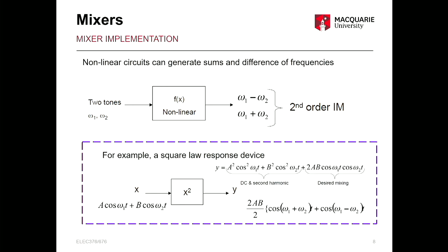So implementing the mixer. We told you that the non-linearity is what makes the mixer operate, and the best mixer is a square law mixer.